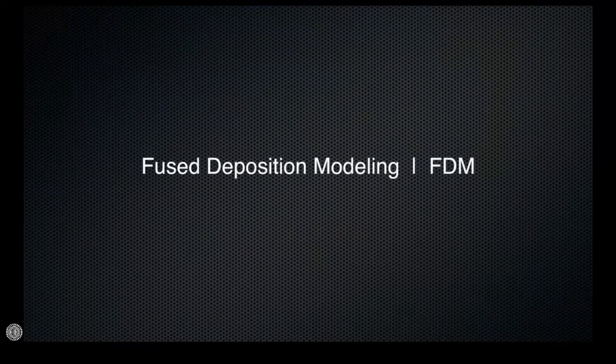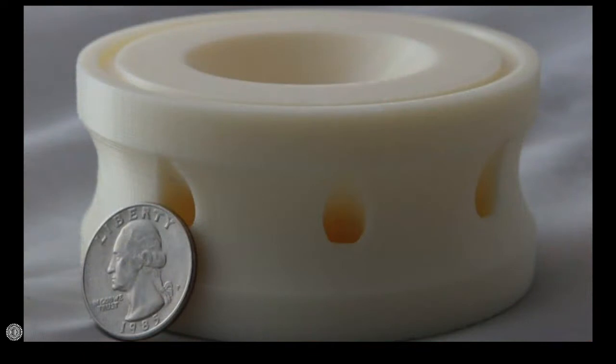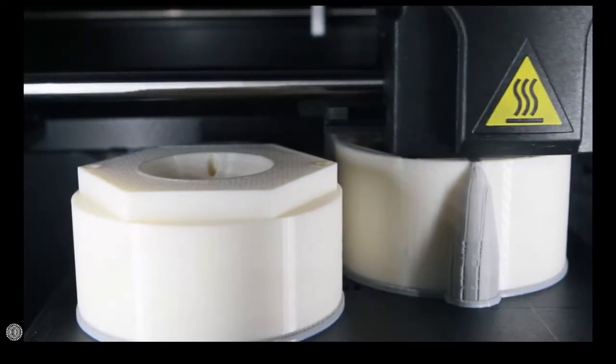The biggest advantage to fused deposition modeling, hands down, is the material. Many 3D printing technologies such as stereolithography, SLA, or even our own objet machines use a UV cured material that simulates plastic. This actually is plastic. So while a UV cured material can be prone to things like warping or breaking down when exposed to UV rays such as sunlight, this will not. The material at hand is an ABS thermoplastic, and with all of these different hobbyist machines entering the market, it's very important to know that not all ABS is alike.